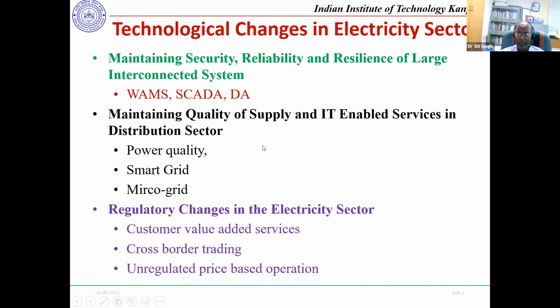So maintaining the whole system, where a lot of things are very intermittent in nature, like the renewable energy sources I'm talking about, wind and solar. They are not deterministic because they depend upon nature. And prediction is one of the challenges. No doubt we are doing the prediction, but if you look ahead hours, predicting at this moment for maybe 1 or 2 hours ahead is very accurate. But suppose you want to do it for 24 hours ahead or many hours, then the error will go up. So in that way, it is a variable.